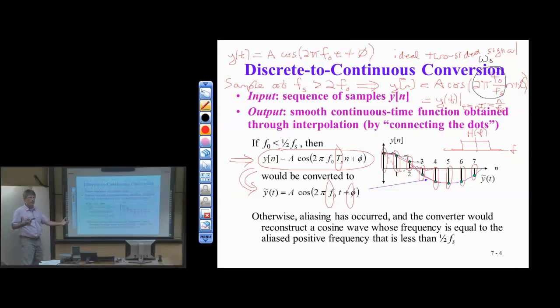I can't do a two-sided sinc, but I can't even do a one-sided sinc. That's crazy. It's a lot of memory. I'd like to make an FIR filter out of this, a windowed sinc. So I can take the sinc and truncate it to say four intervals of time, 4 sampling periods, or 8. In lab, you'll do 4, 6, and 8. And the demo will use this 4 that I'll do later. And it turns out it's pretty good, even after being truncated.